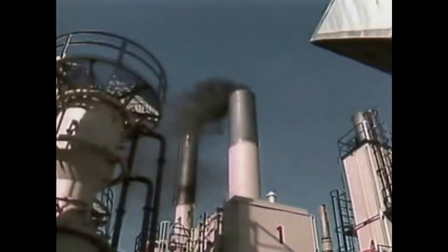This shows up as a smoky, hazy firebox and smoke coming from the stack. This problem is typically corrected by decreasing fuel oil pressure or increasing steam or air to the atomizer. In this topic, we saw how to inspect a furnace and adjust the burners.